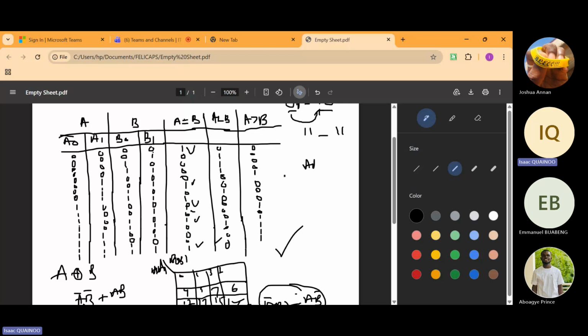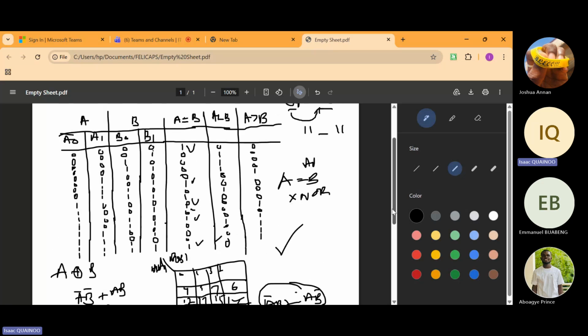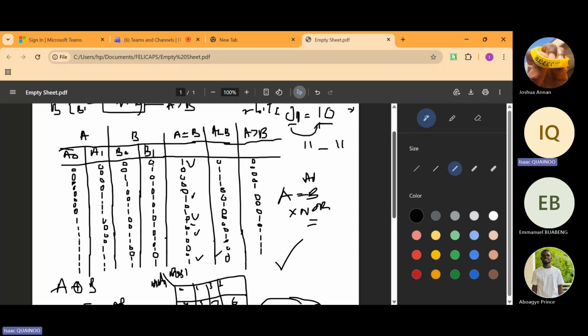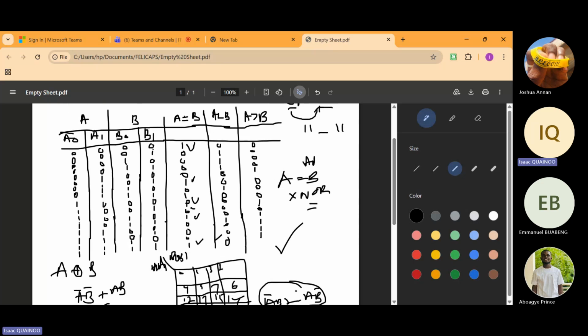So whenever you are dealing with magnitude comparators, we said that equality is always established using an XNOR instead, not an XOR. So it's always established using an XNOR. Please remember I stated this earlier. Do you all recall that I stated that for equality we use an XNOR exactly? So whenever you are dealing with A equals B, don't bother yourself drawing tables, etc. Just take an XNOR operation of all the inputs given.